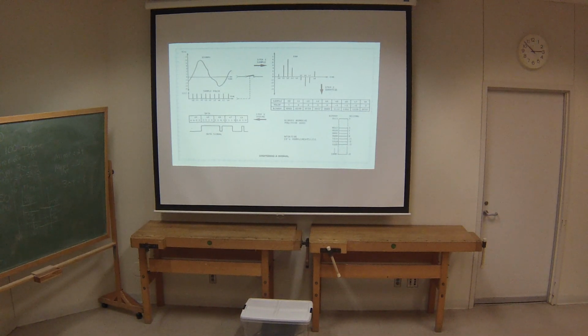It stays at that voltage for, and you bring up a good point that I wasn't going to get into too much. The value of that capacitor is extremely important, because you want the capacitor to charge up long enough to provide you with a nice little pulse there, but you don't want a step. Yes, the quality of that capacitor is extremely important.